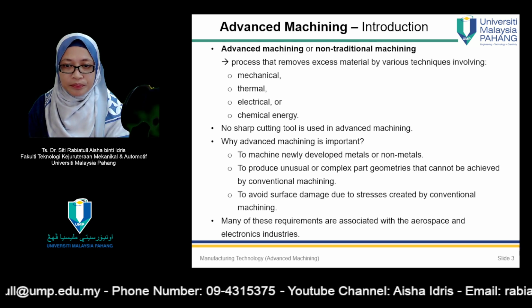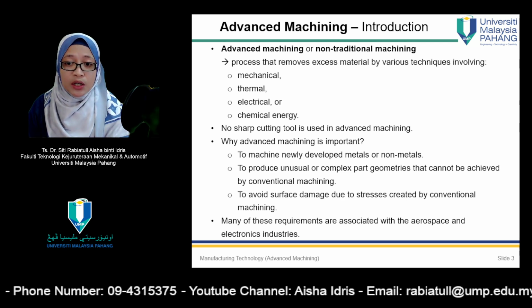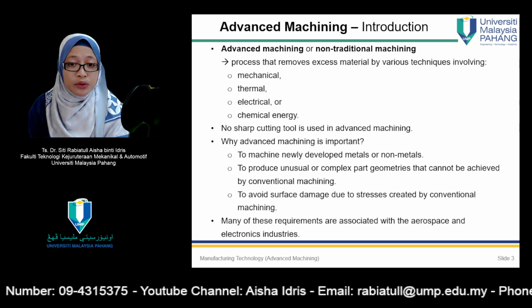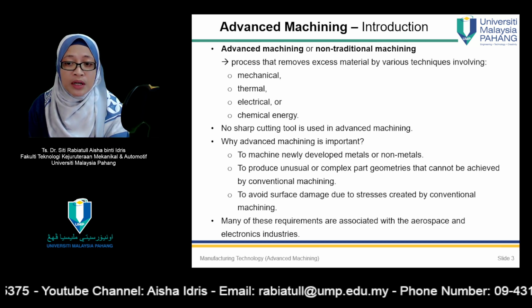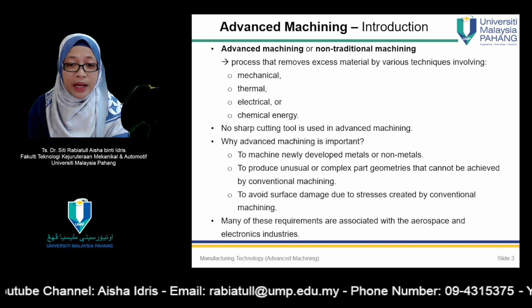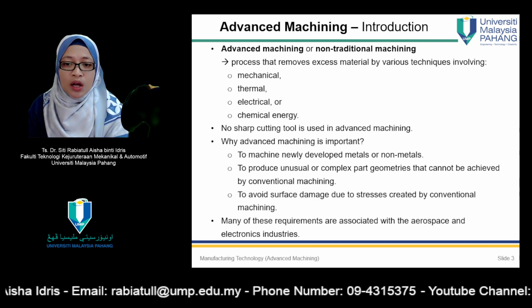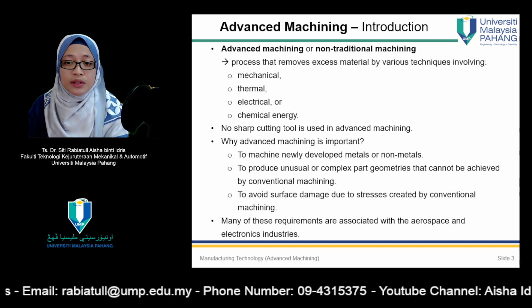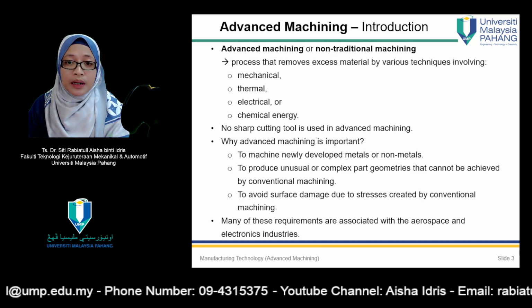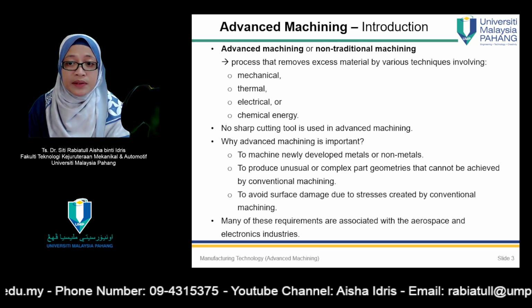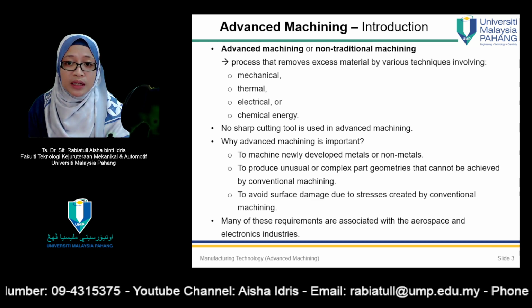The non-traditional processes are often classified according to the principal form of energy used to effect material removal. By this classification, there are four types. Number one, mechanical energy in some form other than the action of a conventional cutting tool is used in these processes. Erosion of the work material by a high velocity stream of abrasives or fluid, or both, is the typical form of mechanical action in these processes.